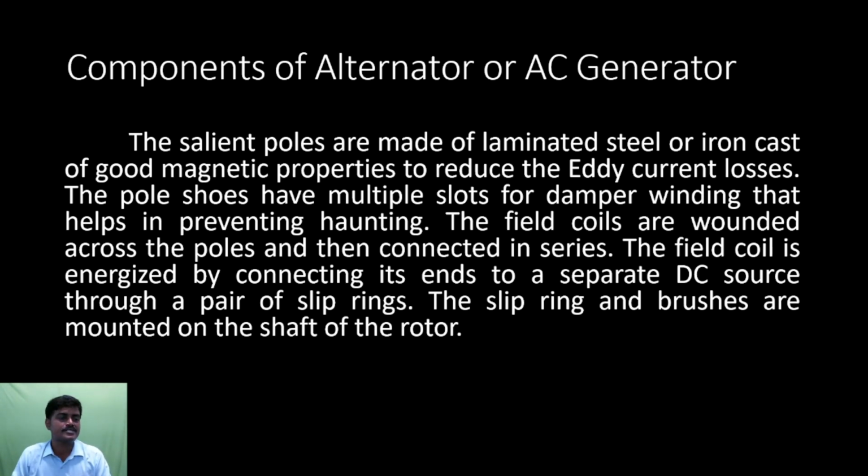The field coil is placed in the rotor only, so in order to produce a magnetic field while it is rotating, we inject a small amount of DC current from an external source using the slip rings and brushes. Nowadays, the recent trend is to use the brushless alternator, which we will discuss later.